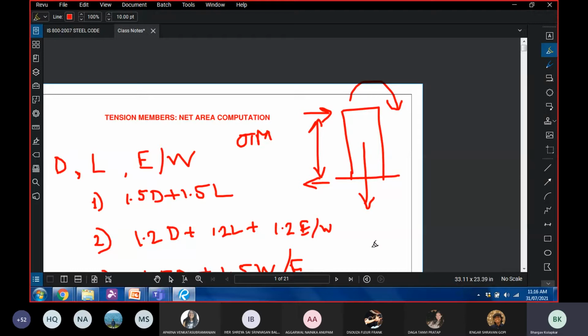You try to apply a load at its top, it will overturn very easily. Now you fill that bottle with water and then try to overturn it. You will need a larger force to overturn it, which means that the weight of that bottle, or whatever is in that bottle, matters, and that is what resists overturning of that bottle.